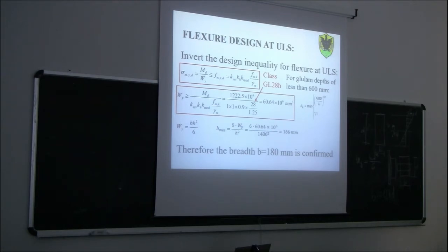So remember, always follow standard sizes. It's more or less like for steel. You can have an IPE 140 or an IPE 160, nothing in between. And similar here for timber. For timber it's easier to have something in between, but it's more expensive, because they have to start from a bigger cross section and then you have to cut it. Okay, is it clear?